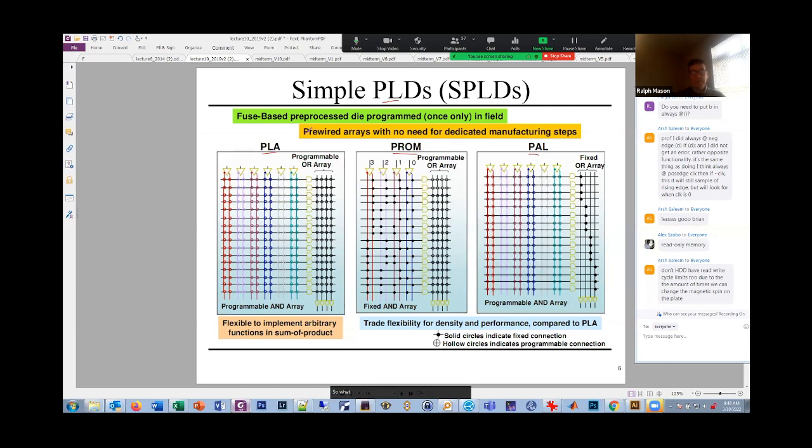So what's a PLA? Instead of putting AND gates and OR gates on our circuit, we want to make an array of ANDs and ORs so that we can do any sum of products function. So we can build any logic. No sequential circuits, just logic, but we can build very complex logic. These little AND gates right here basically have a bunch of connections. It's not shown here, but there's 1, 2, 3, 4, 5, 6, 7, 8, 9, 10, 11, 12. That's a 12 input AND gate.